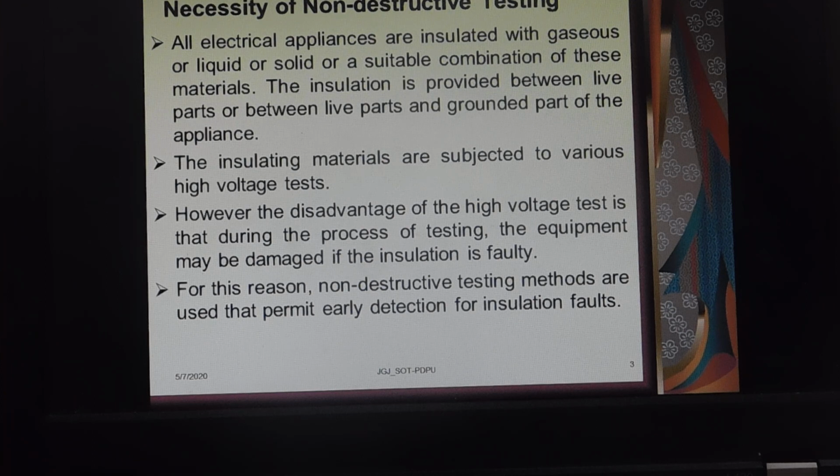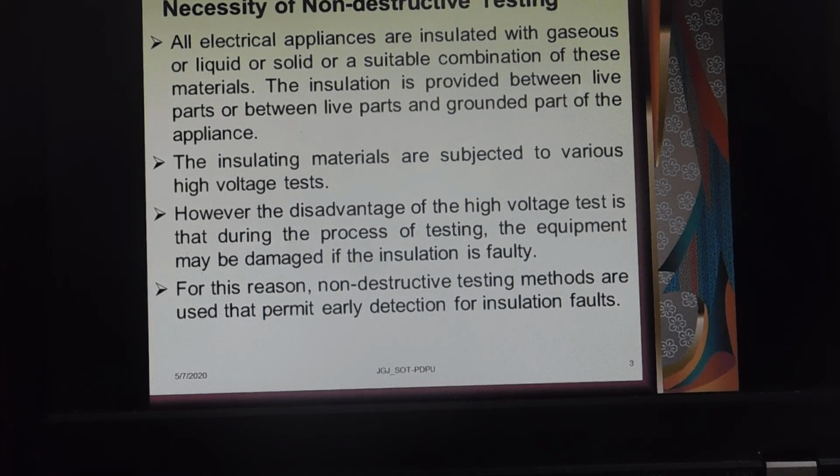The insulating materials are subjected to various high voltage tests, but the disadvantage of performing the high voltage test is that during the process of high voltage testing, the equipment may be damaged if the quality of the insulation is not good or faulty. So for this reason, non-destructive testing methods are used, and that will permit early detection of insulation faults.